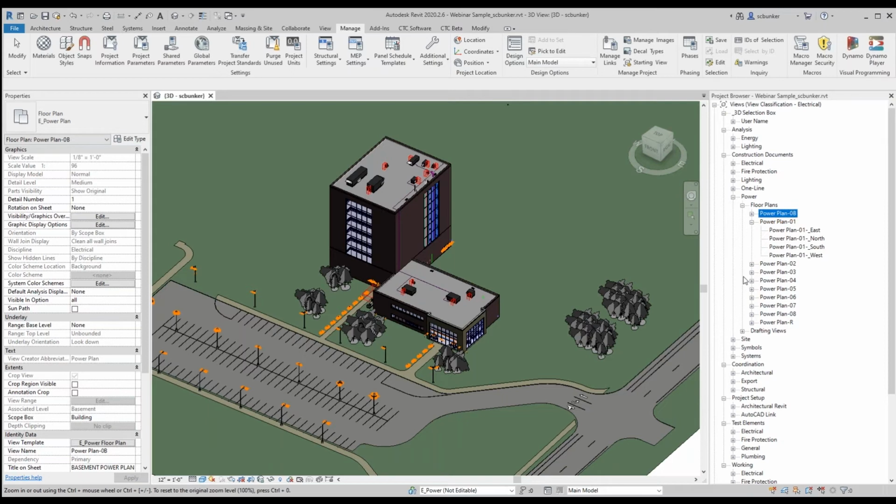But if you're working with a smaller building, which most people probably are, you also do not have to go through the tedious task of deleting all of this stuff. In the content that's provided is a Dynamo script that you run, and you just step through a series of questions saying what floors you need, whether you need the north, south, east, and west dependent views, and even whether you need certain subdisciplines.